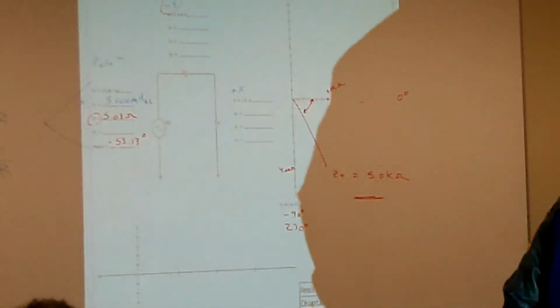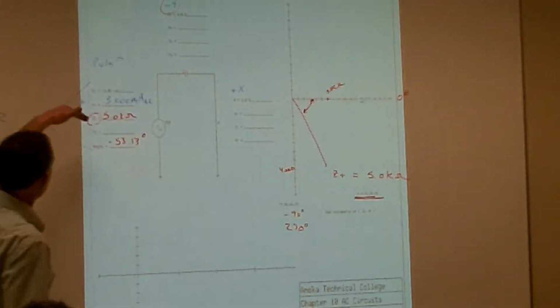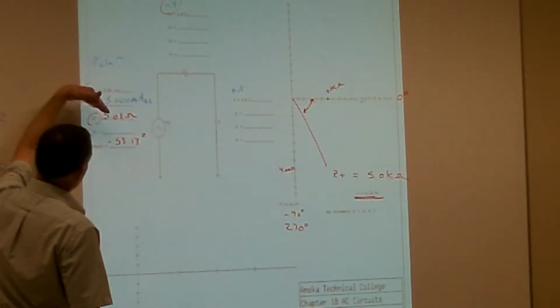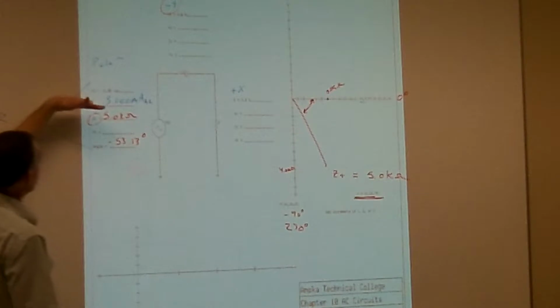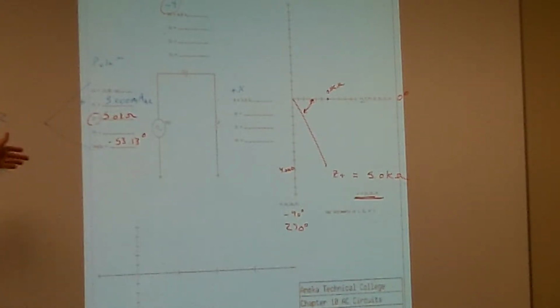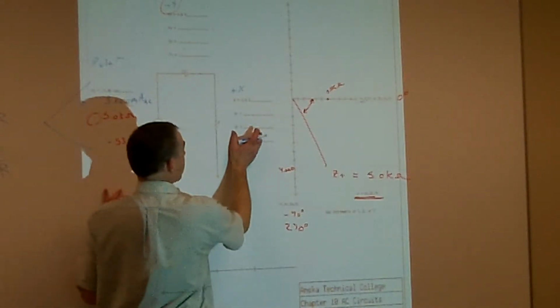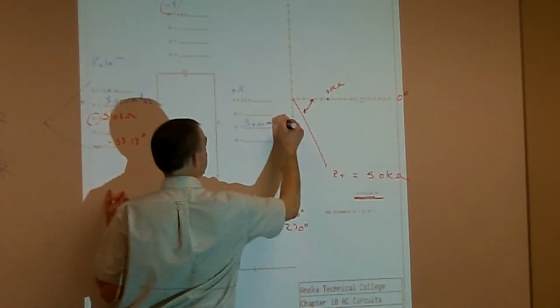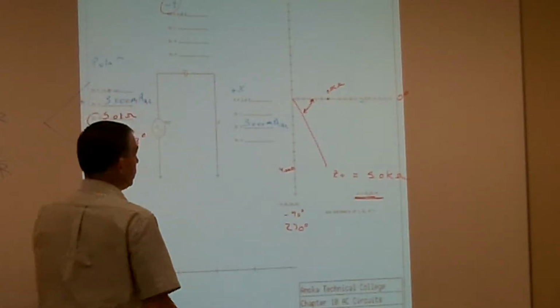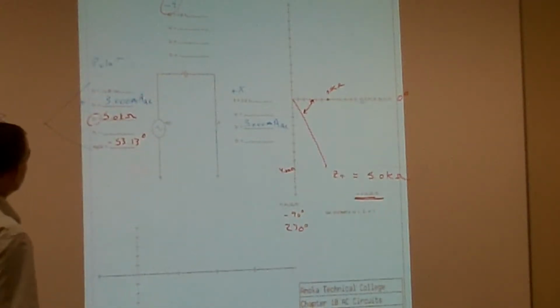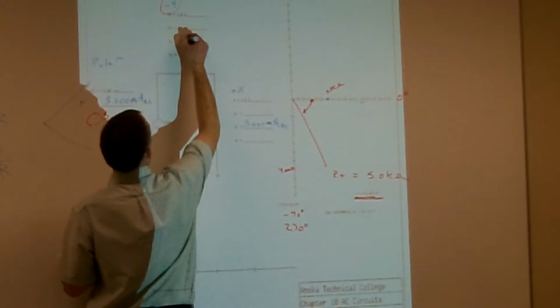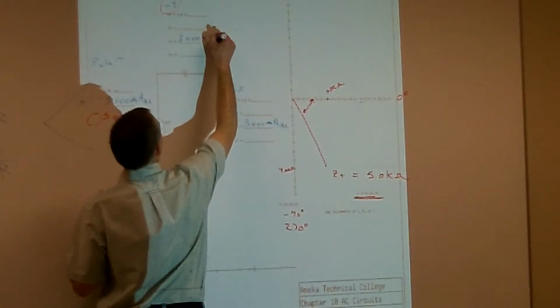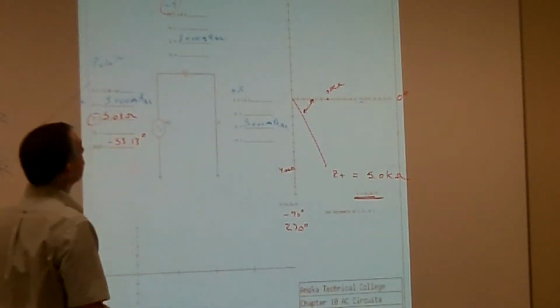All right. So that's our basic Ohm's law. We can still use Ohm's law at that particular component. Then, just like we did back in DC, what remains constant in a series circuit? Current. So what's my current going through my resistor then? 3 milliamps. So that still remains the same. Nothing happens there. So I'm going to put in 3 milliamps there, and my 3 milliamps AC here.